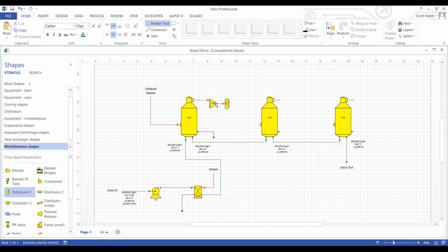So the purpose of this, again, is the receiver allows us to bring other vapor streams into this header. So for instance, and we'll do it in a little while, if you had a flash tank here flashing the condensate, you would want the vapor from that flash tank to come to this receiver. And then the distributor allows us to take vapor away from this header.